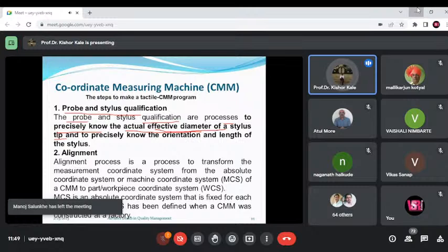This is the datum. From these points we'll form a plane over here. From this plane, we'll take 1, 2, 3 points that best fit to form a single plane. This plane is moved in such a way that it coincides with your CAD model. So this is called correspondence for localization.